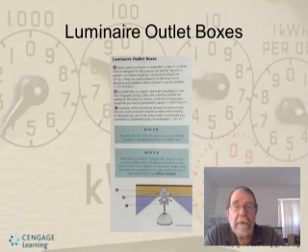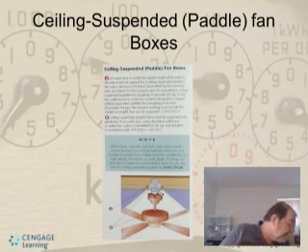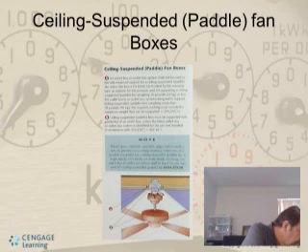Okay. Ceiling fan is a little different. An outlet box or outlet box system shall not be used as the sole means of support for a ceiling suspended paddle fan unless the box is 1. Listed, 2. Marked by the manufacturer as suitable for the purpose, and 3. Supporting a ceiling suspended paddle fan weighing 70 pounds or less. Fan outlet boxes or outlet box systems designed to support ceiling suspended paddle fans weighing more than 35 pounds, the required marking must include the maximum weight that can be supported.